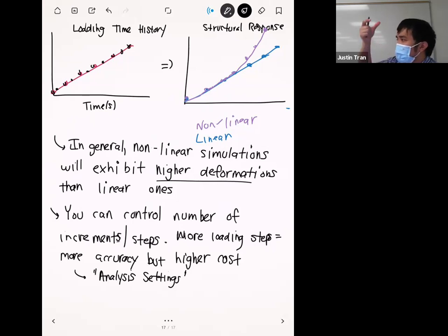No, I think it's under static structural. Under static structural, there's a button called analysis settings. And so we haven't done anything with that so far in the class, but all of these settings for how you apply the loads, whether you turn on large deformations, all of that is within that tab. Okay.